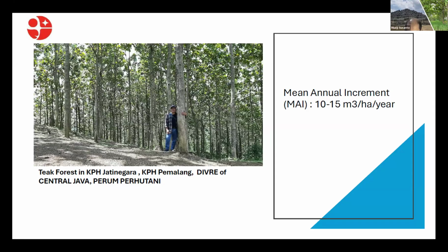JPP teak is well known for its fast-growing characteristics, and its high wood quality is comparable to conventional teak at a similar age. However, some studies indicate that the wood properties of JPP teak, particularly at younger ages, may be slightly inferior to older conventional teak in terms of drying properties and basic wood properties. Despite this, JPP teak can be a viable option for various applications, especially when considering value-added treatments like densification, thermal modification, and preservation.